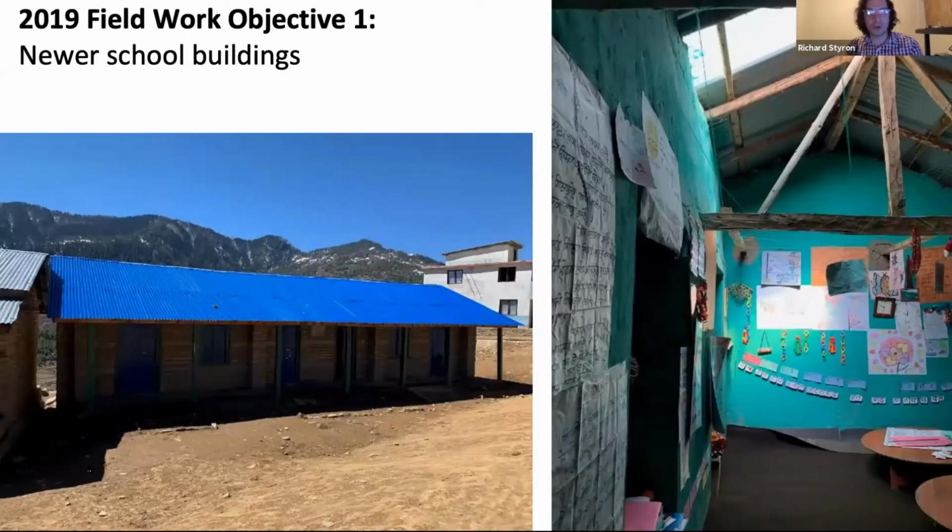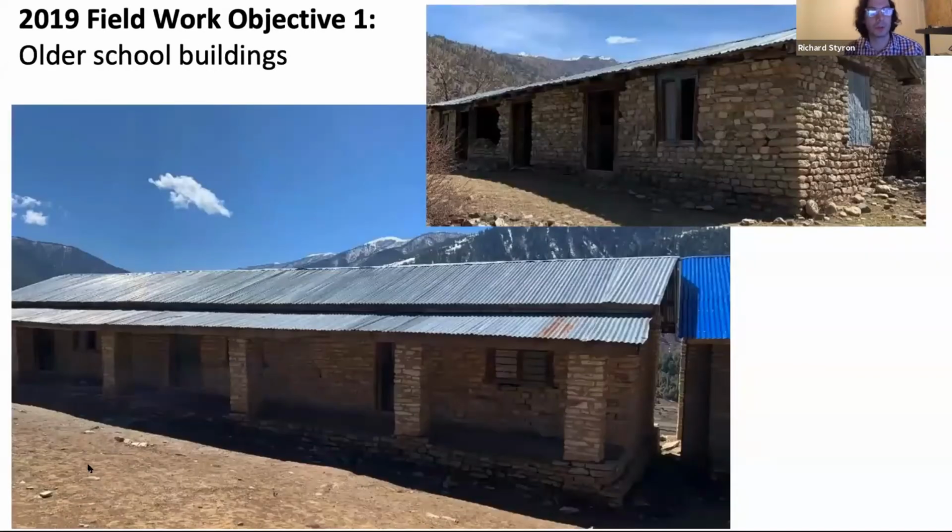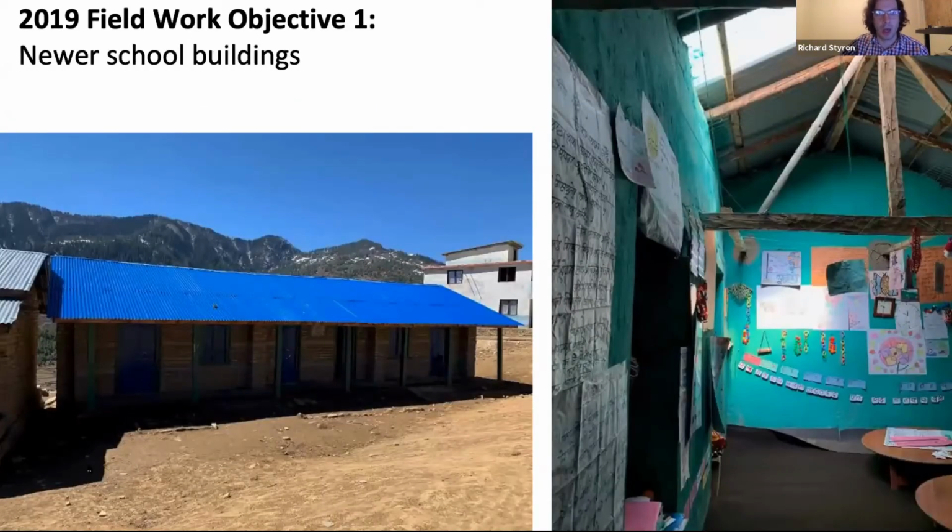So we're also not only looking at residential buildings, but at buildings that serve in a larger, more civil capacity. So we have older school buildings that we've surveyed. And these, again, are simply stones that are stacked with mud holding them together. They have a little bit of wood involved in the door and window frames, but not a lot of through-going wooden infrastructure. Newer school buildings are a bit better. They have more wooden framing holding up the roofs and running throughout the buildings.